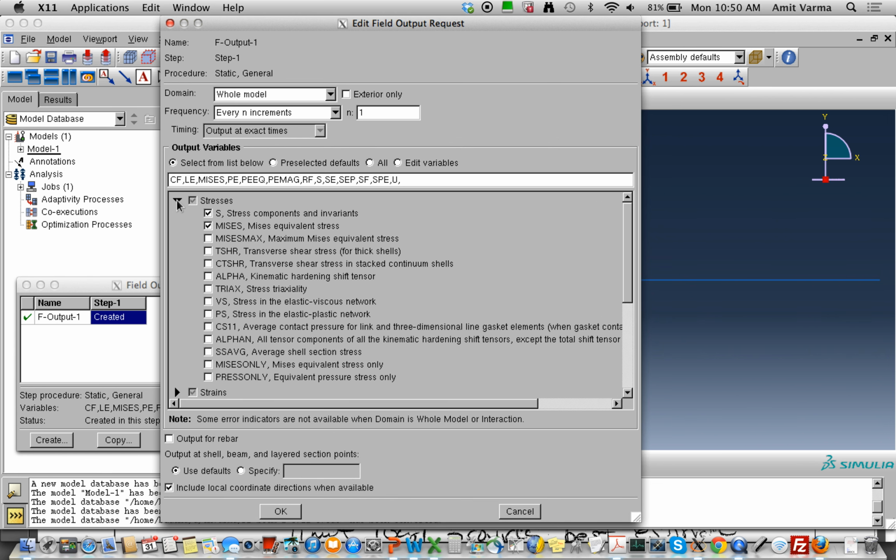I almost gave you a problem where there was a thermal load, so it would expand and it would get an axial force, and then I decided that maybe I was making your life too difficult, so I gave up on that. I just gave you the axial force of 0.2 Py. It's easy enough. You can calculate 0.2 Py, apply it. Just make sure that you don't restrain it at that foundation, otherwise it won't apply the axial force.